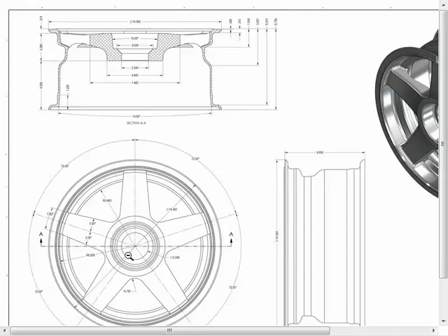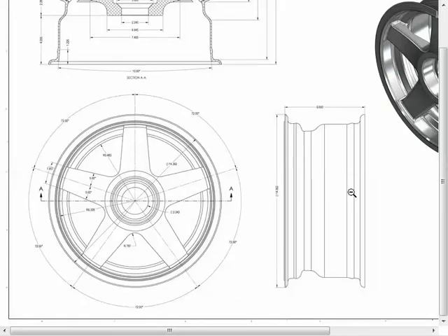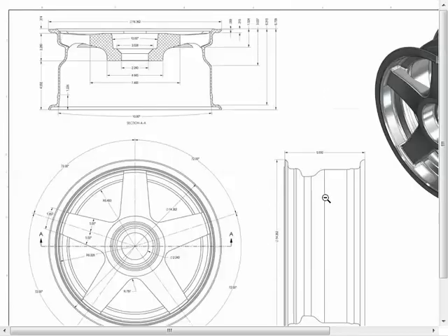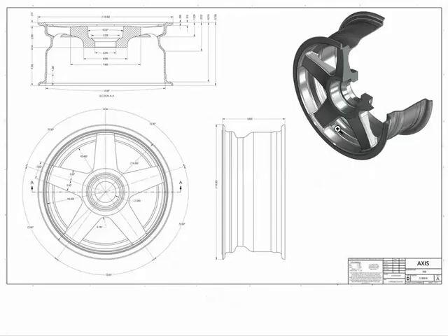So here's a front view of the car wheel. A lot of the angular features are dimensioned in this front view. Height information, notice all kinds of edges have been dimensioned all from the top of this wheel. There aren't very many dimensions in this right hand view, but the overall size of the thing has been placed in this right hand view, together with the isometric, which you can sort of see right here. See if I can get this thing to go back out.